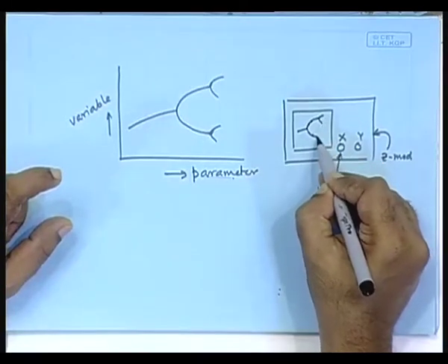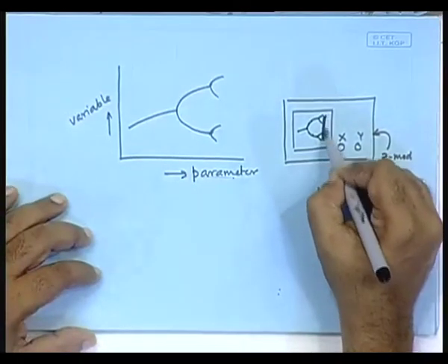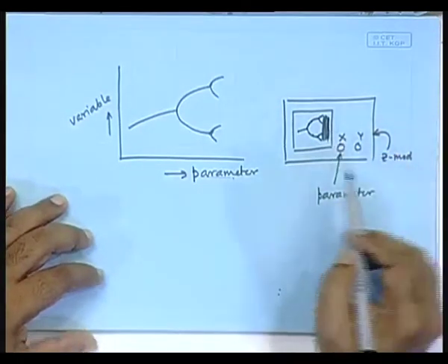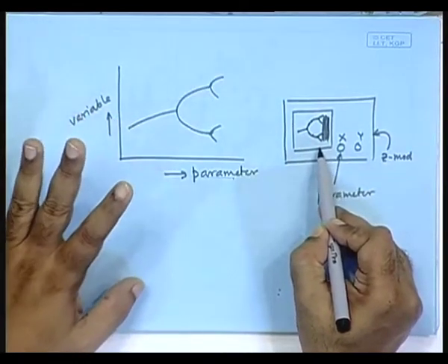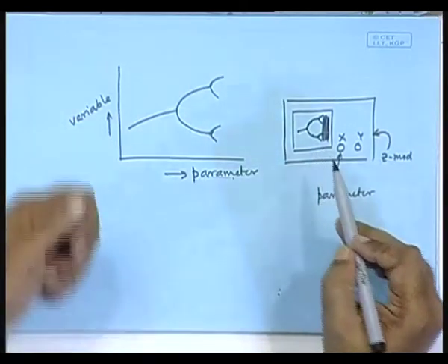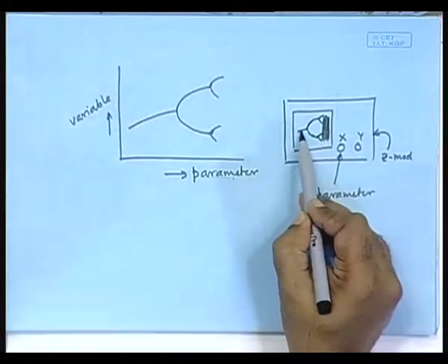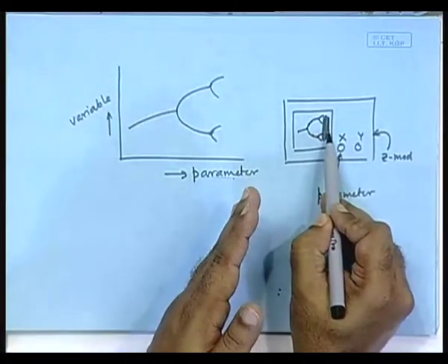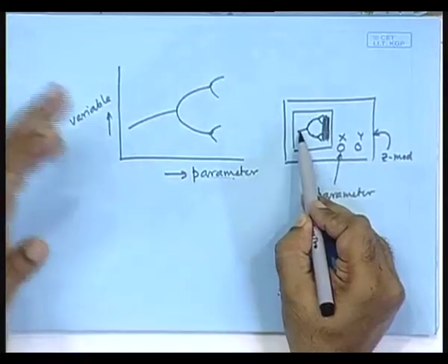Again, if it goes into period 4, you will get something like this. If it is a chaotic orbit, you will get a smudge. So, the whole bifurcation diagram actually appears on the CRO screen, but not at the same time. As you move, this bifurcation diagram actually sweeps through, right? And when it comes here, this is no longer there, it has vanished.